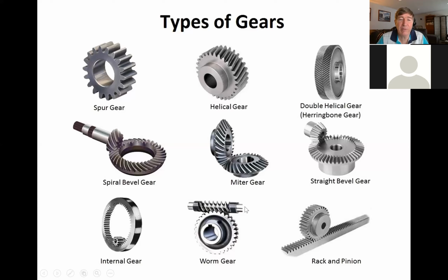But on the top here, we take what is basically a screw or a bolt, if you want to think of it that way. We've taken this cylinder on the top and cut these screw-like teeth into it, and they're the right shape, so they interface with the spur gear below it. So when you spin the shaft here, it ends up turning the gear below it. So yeah, worm gears are actually very, very cool.